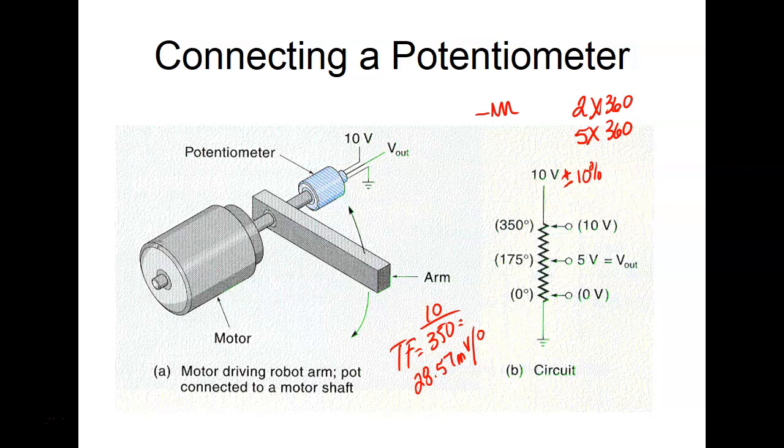I'd print out a compass. I would put the pot on there. I would turn it all one way and put that on 0, and then turn it until it stopped. And I would literally measure the amount of degrees that pot actually went to. That way, your measurements and your calculations would be really close, right? You understand?